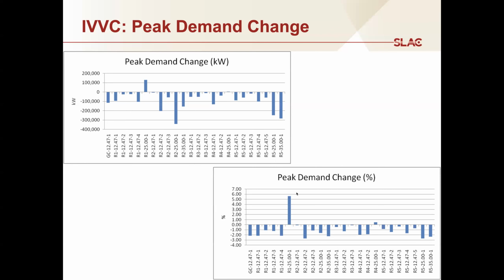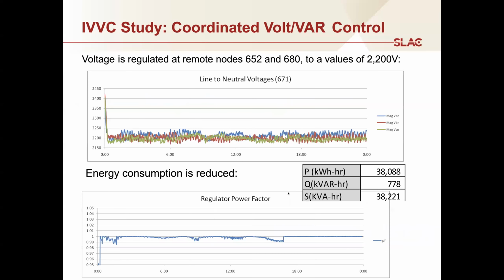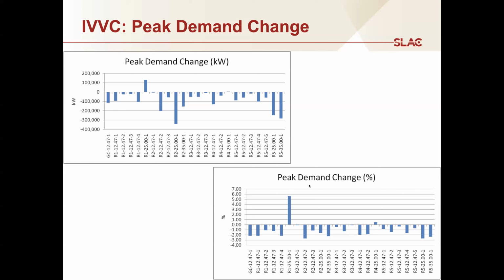And you can see that the percent change in the peak demand is pretty significant. It's not a trivial amount. So the takeaway is obviously that volt-VAR control is not a universal fix. And in other cases, it simply doesn't do anything at all, or hardly anything at all. And so it's not always going to be a solution that you would apply everywhere.